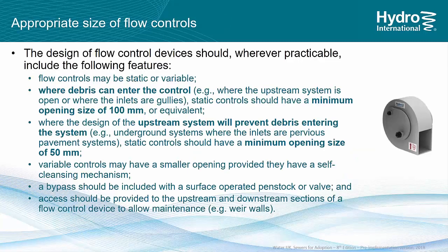With regard to sizing flow controls, with the way in which the built environment now works, we start looking at having smaller and smaller flow control discharge rates coming off of the site. This is starting to come through more and more in legislation with lead local flood authorities, but is also now being shown in the upcoming Sewers for Adoption 8 in the pre-implementation edition that's already been published, but it's due to become live as of April next year.